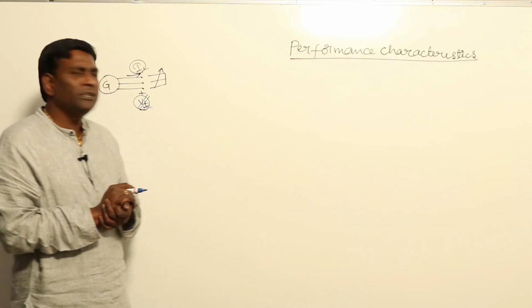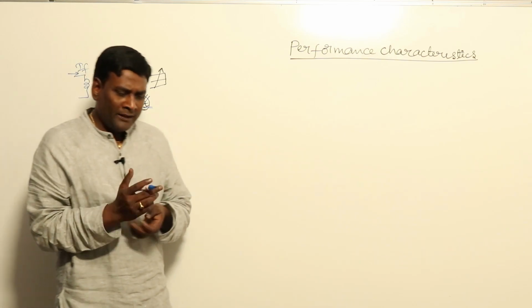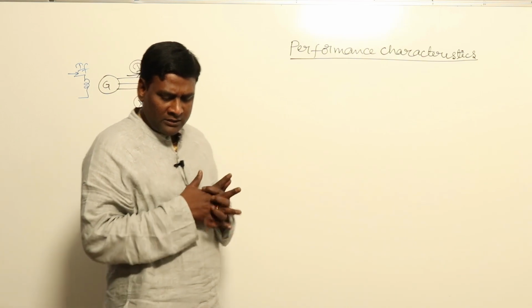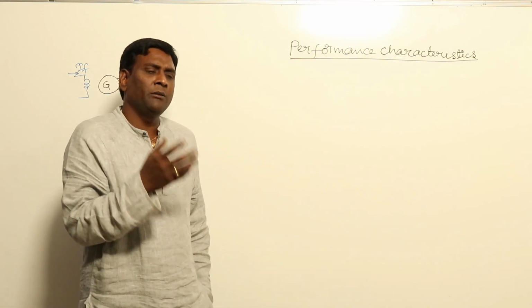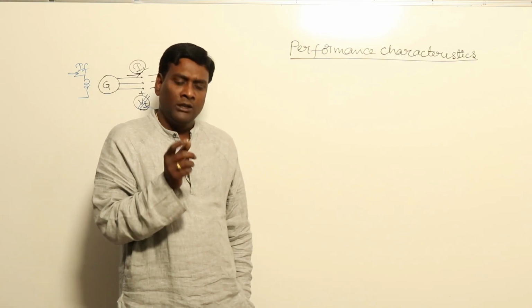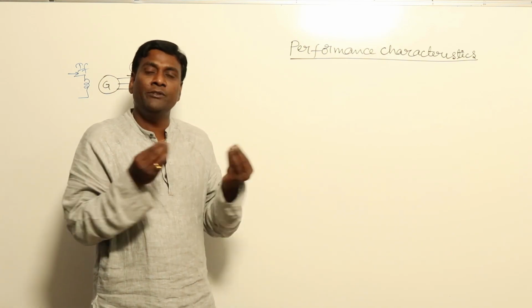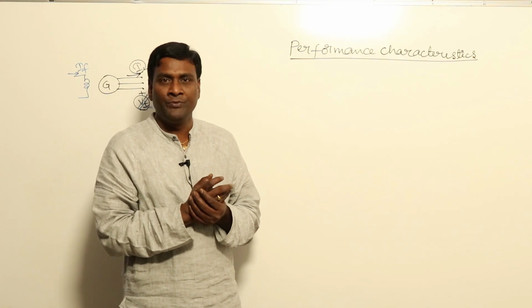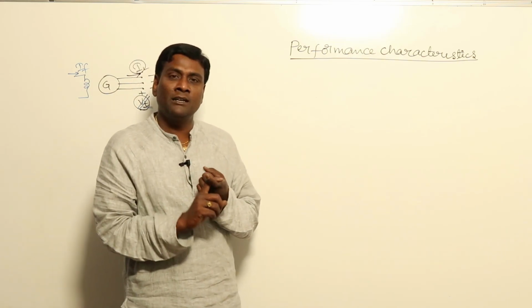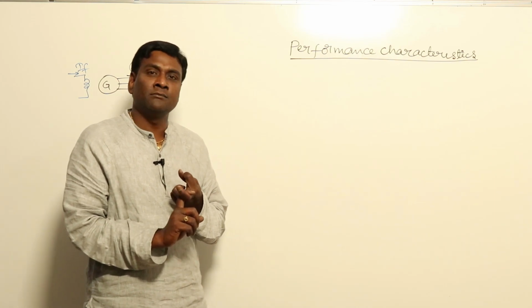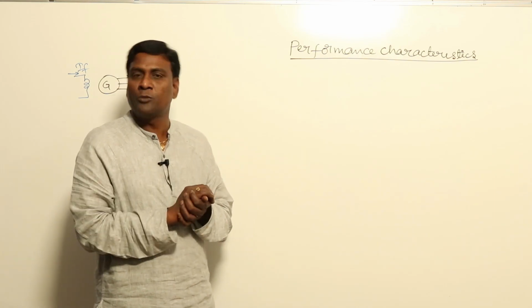And one more thing, the load characteristic, will come. As of now, we cannot say its significance, but it will be used to differentiate between Xar and Xal. In total, in the synchronous reactance, Xal leakage will be there, and because of armature reaction, some X will come. Already we have seen this in our previous videos.